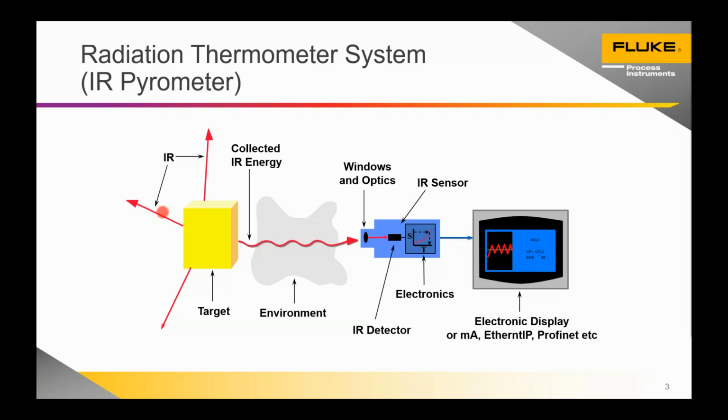There's different technology for that, and we're guiding the energy to the detector by means of windows and optics. They can be plastic, glass, crystal type of components, but we're purely passive. If you ever see a laser or an LED from the sensor, that's purely a guide to where we measure. We're not shining anything out to receive something back.